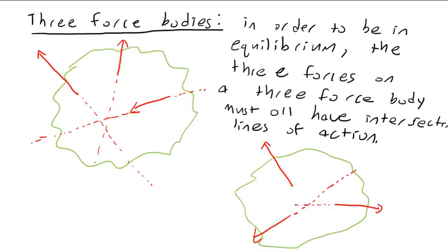It simply says that the lines of action must meet at some point. That way, we will not have only two not generating moment at one point. All three of them will not generate any moment at that one point. All right, yes. This is the case for 2D and 3D. With 3D, you'd get a bit more complicated, but this is generally concerned strictly with 2D right now.